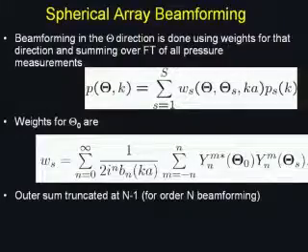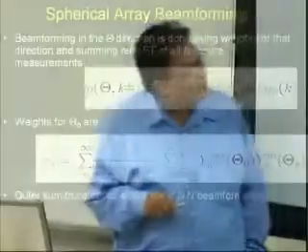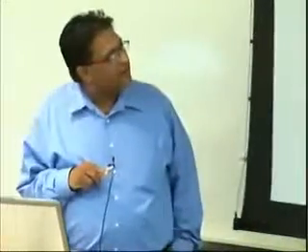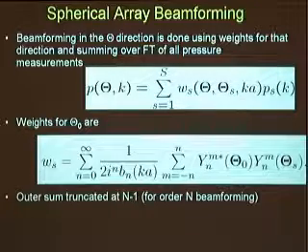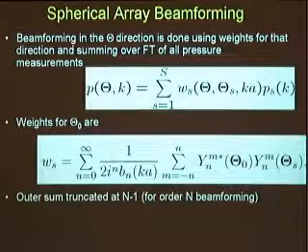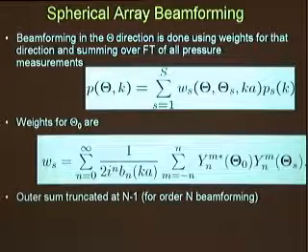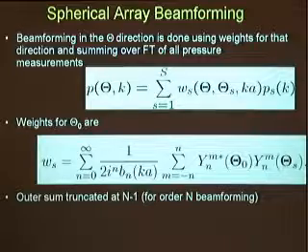Okay. So now let's step back and see how you do spherical array beamforming. Suppose you want to find the beam response of this array in some particular direction theta, and you've recorded signals now at S microphones, which are spread on the surface of the sphere. You compute these weights and you sum up and you get the response in that particular direction.